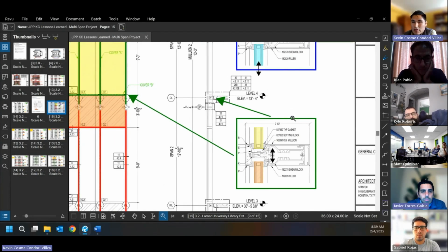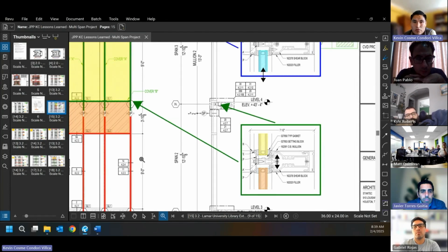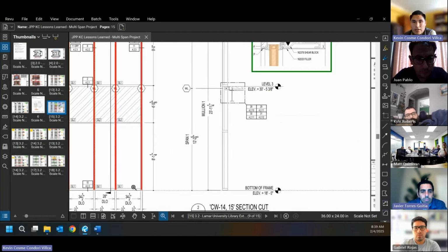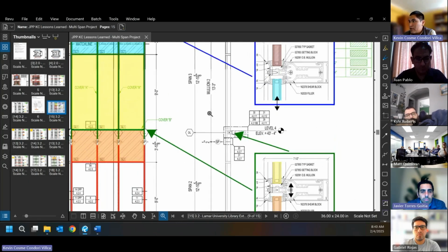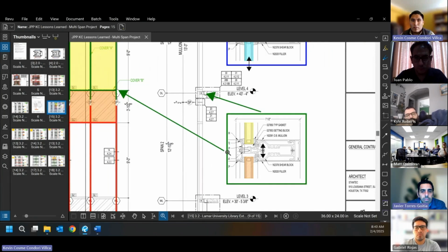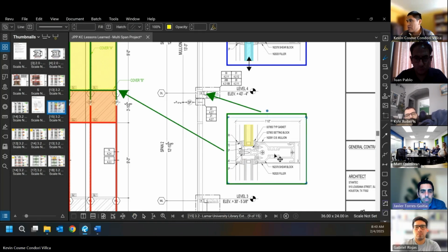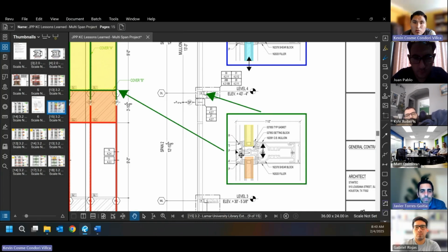For this mullion outlined in green, since the red mullions are supported at the slab here, they will remain static while the slab at level 4 above the splice deflects. We will see the following movement in the mullion, something like this. So in this case, if the movement exceeds the mullion's clearance, we would end up resting on the glass, transferring stresses to it.